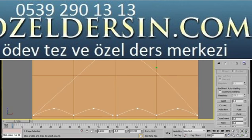I'll just undo that. Make sure I've got it selected in the corner. I'm just going to drag the handle straight up and then I'm going to stretch it out. I'll stretch it to the right, something like that. Let's do the same now on the left hand side. I'll select this vertex. I'll change it to Bezier corner. I'm going to grab the large handle, bring it straight up till the handle's straight, and then I shall stretch it to the left. There we are. That was easy. Look at the nice curve we have there.